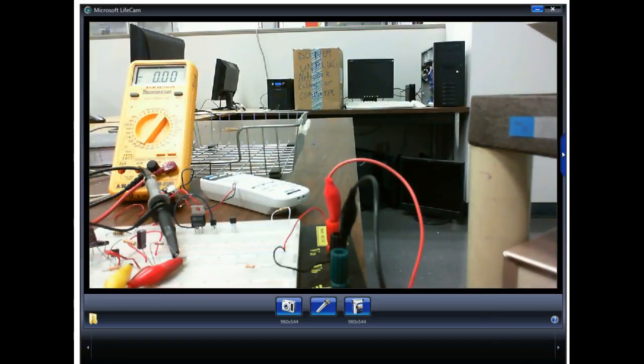So sometimes we have 2 parts that appear to cause the same situation. Of course, what we would do is take out one of them and measure it, see if it's okay with our ohm meter, right? But remember, try not to measure these in circuit. Rule of thumb: if you measure in the circuit and it measures okay, we assume it's what?